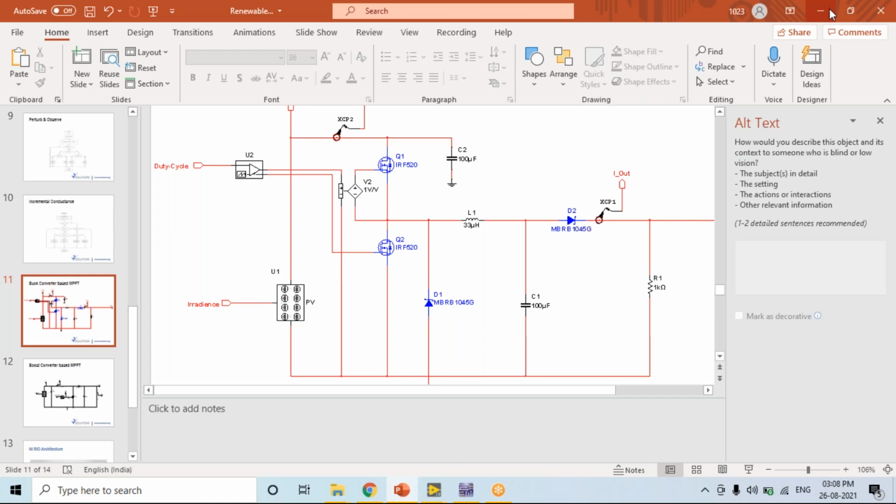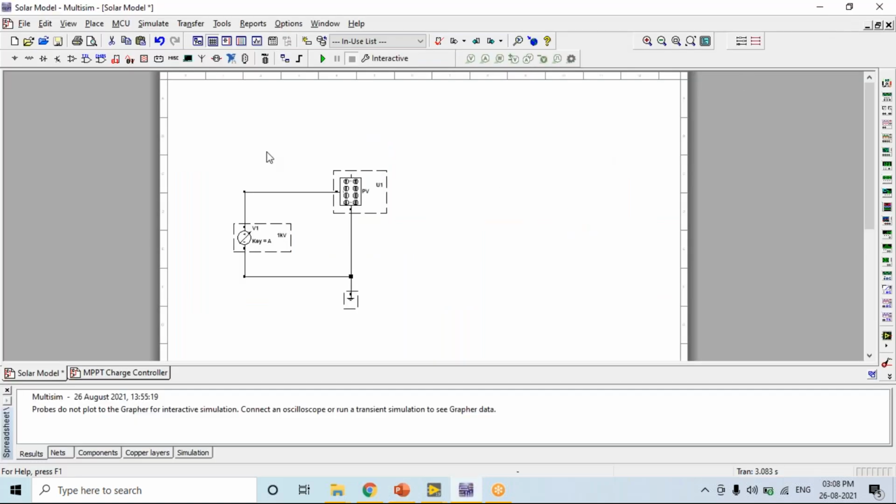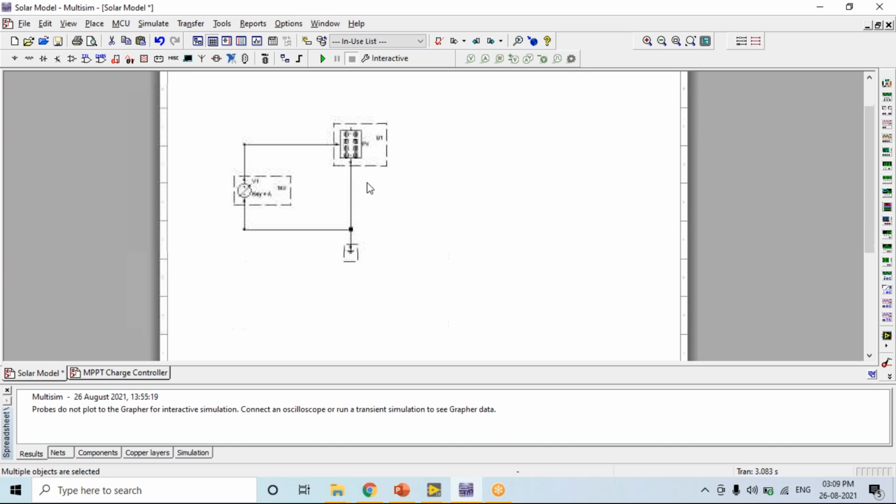So yesterday we saw that in order to generate the waveforms, the inputs for your inverter, we directly gave from LabVIEW to here. But not all frequency controls will be supported from LabVIEW. Sometimes for simulation, we need to make use of Multisim-based sources for PWM generation, and yes, we do have certain sources available in Multisim to do just that.